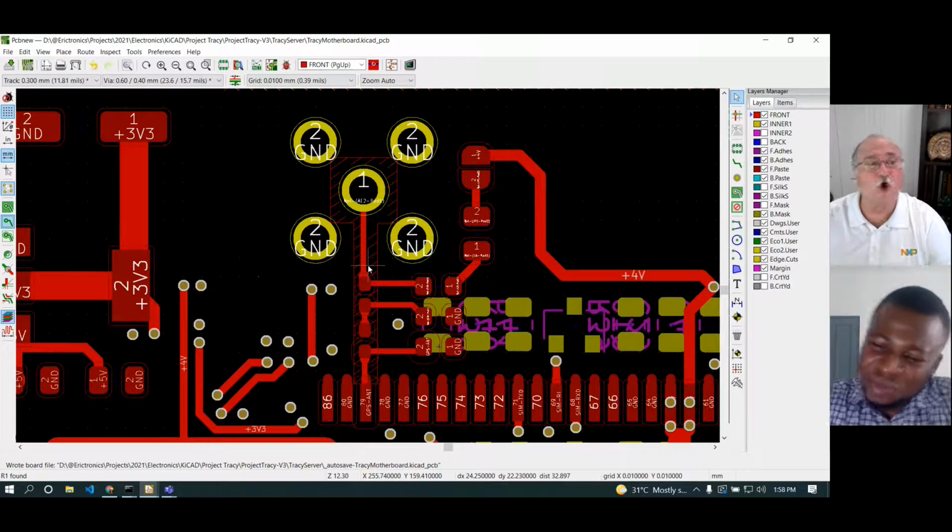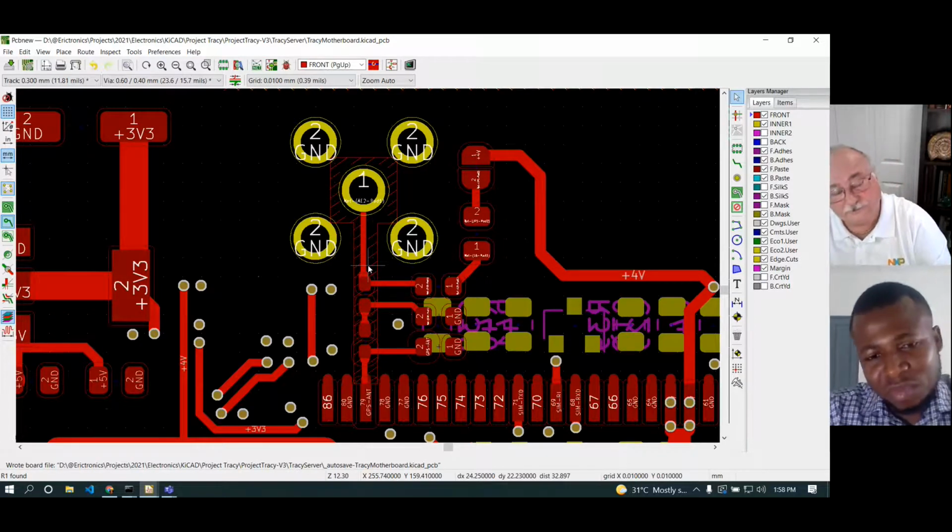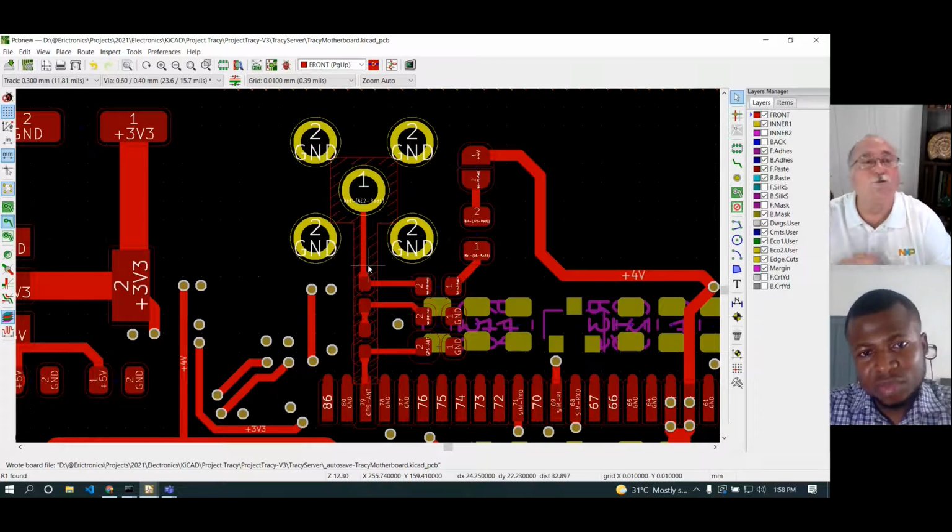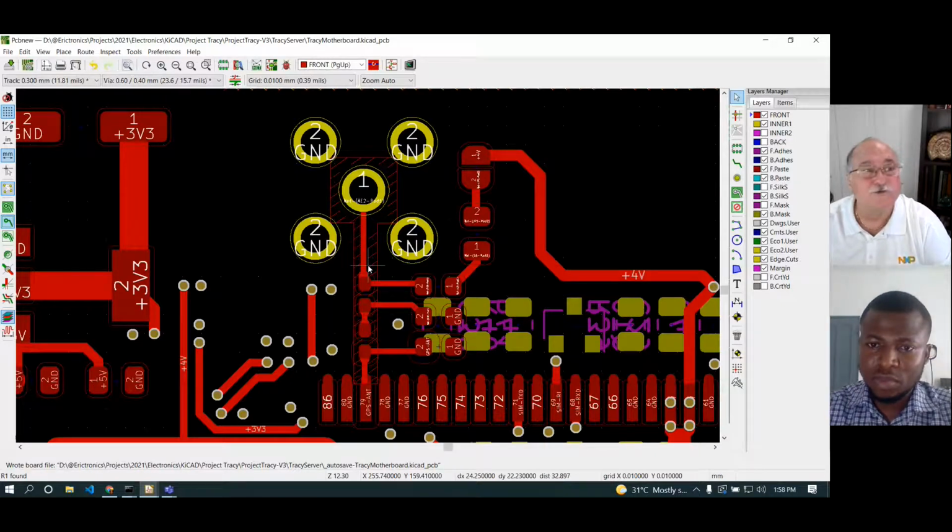Everything was so large relative to the switching speed of the transistors, it was always lumped. So you could do really bad things and it didn't cause failures most of the time. Now we have things that switch very fast, and the structures on the circuit board are very small relative to those switching speeds. So you have to be very conscious of what is or is not lumped.